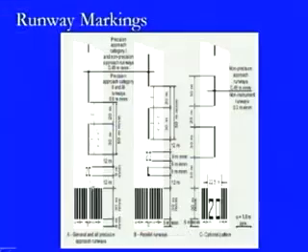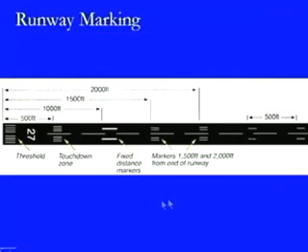These are the things which have been shown here. There are a number of different ways by which this marking can be shown, like 20 being defined here, and it is 9 meters long in this form. Another way is the 20L condition. So, 20L can be written as 20 with L at the bottom, or it may be 20 and L in continuation. Those are the 2 ways by which it can be done. And the third way is that we can use this 20 within the threshold markings. So, there are different ways by which the runway markings can be provided.